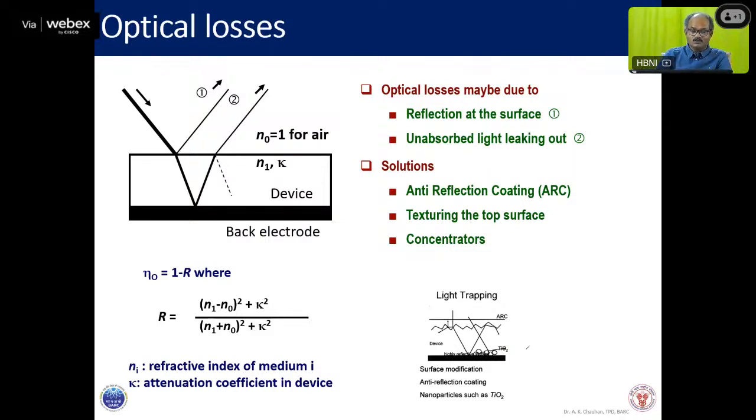All those electron and hole pairs are sent to their respective electrodes without any recombination, and then afterwards all those electron and hole pairs move through the load. That is the ideal process. If everything is ideal, we will have 100% efficiency, but ideal things are not possible. Let us see what are the losses which are invariably going to happen.